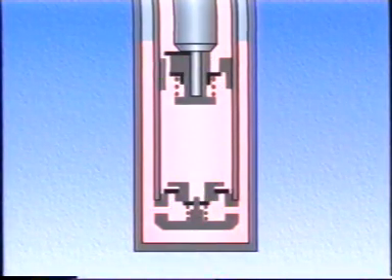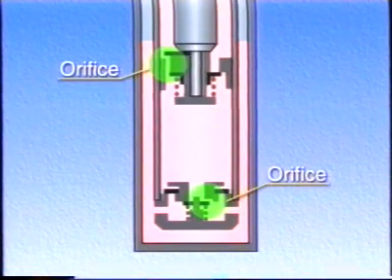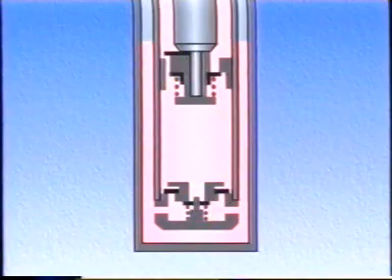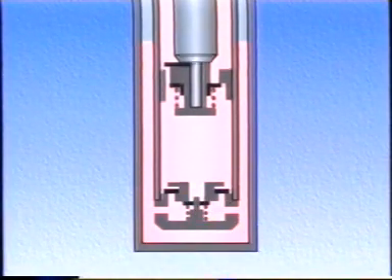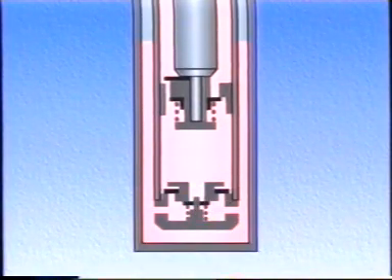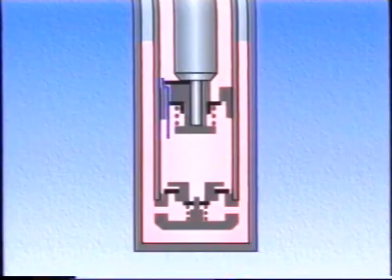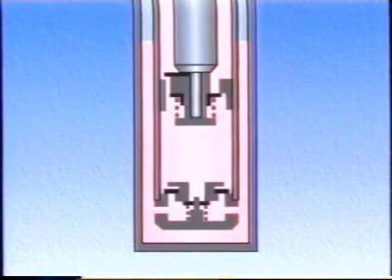There are orifices in both the piston and base valves which allow fluid to flow at all times. If the speed of the piston rod is low, this mechanism allows the flow to generate a slight damping force with the piston valve and the base valve closed.